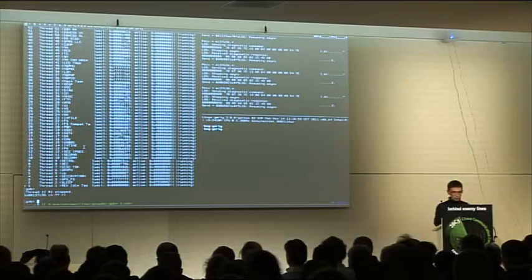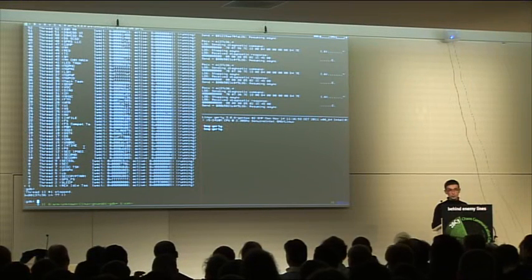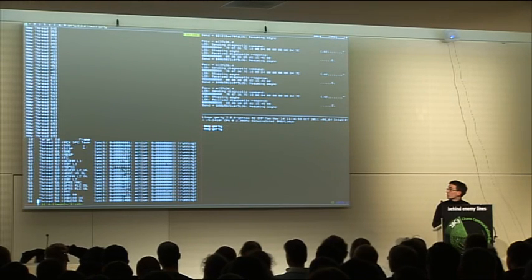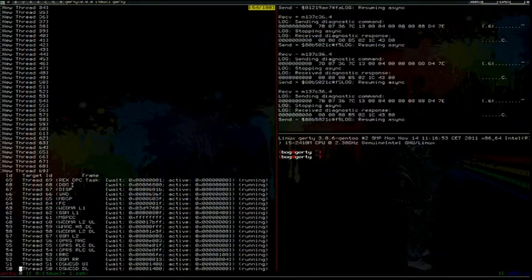So when you debug the baseband, actually you have, as I said before, a watchdog task, which is constantly checking whether tasks are alive. So if you break a task, for example, with a breakpoint or something, the watchdog will detect it and reboot the system. So you have first to account for this and break the dog task.